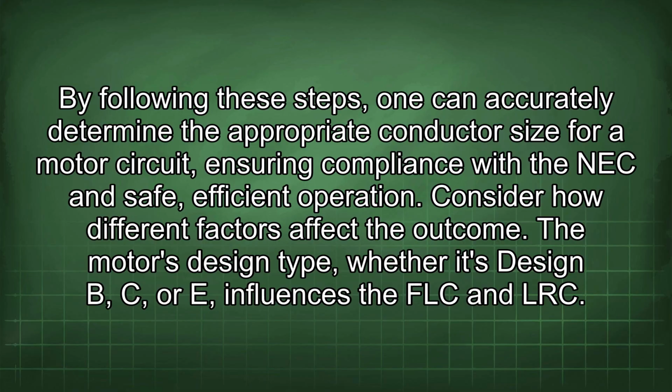By following these steps, one can accurately determine the appropriate conductor size for a motor circuit, ensuring compliance with the NEC and safe, efficient operation. Consider how different factors affect the outcome. The motor's design type, whether it's design B, C, or E, influences the FLC and LRC.